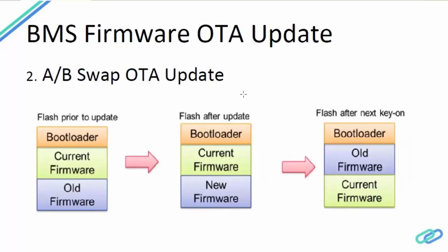The latest microcontrollers that have come up in the market can execute the current firmware while the bootloader updates the latest firmware. There are two partitions inside the flash memory, one for the old firmware and the second for the new firmware.